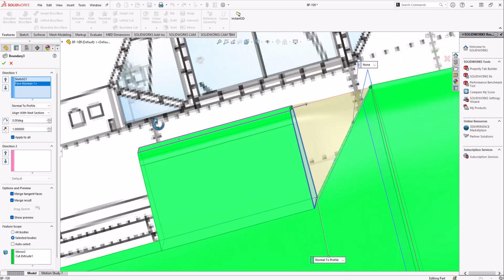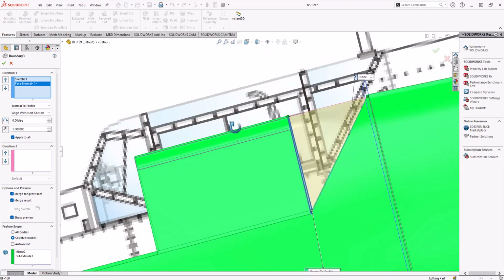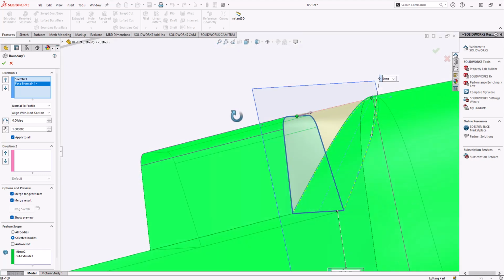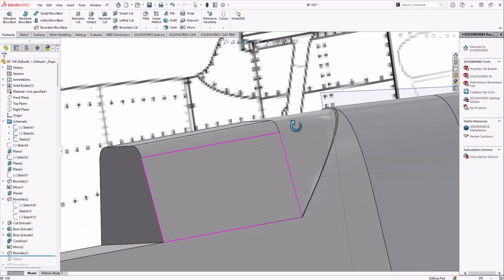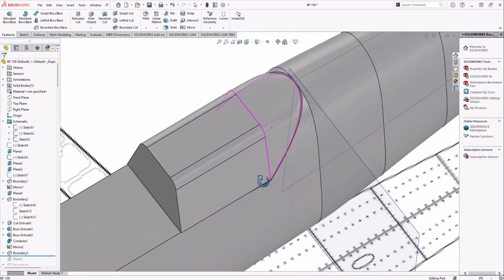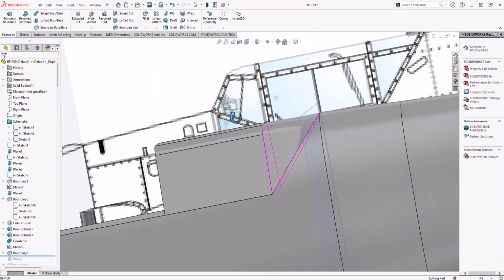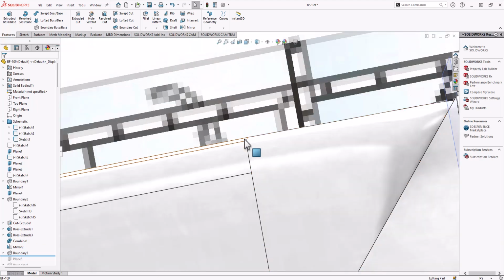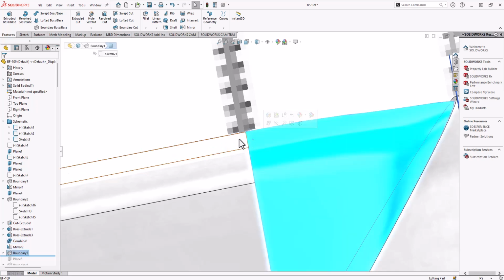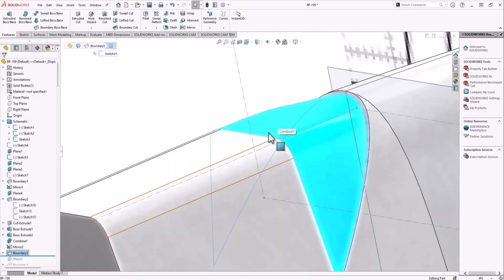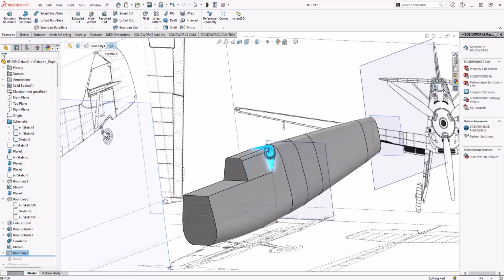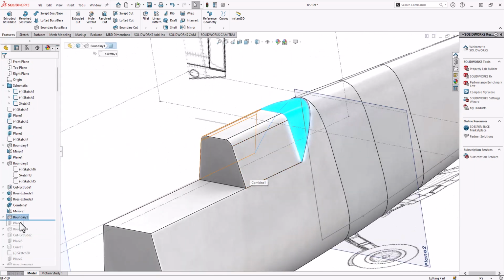So if I do normal to profile, it will have some component that's coming straight out of this face, which makes it look way more organic, like this, rather than having something non-smooth. What this does is it enforces that this and this have the same curvature, essentially, or same slope at the interface, so it's a smooth transition rather than an abrupt transition.